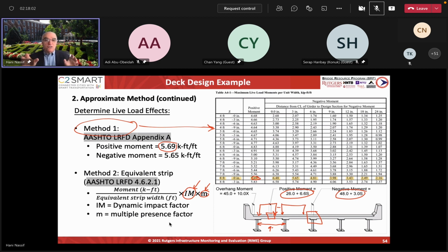In a girder, you can put one truck and then follow it by one truck. The whole girder will deflect under the effect of them. But here, it's the axles. And if you're taking the strip here, the HS20 truck is about 28 feet, so some of the loads will be distributed back to the strip because they have some effect on the strip. They are in the long direction, but you still have to take them into account. But the loads here are 16 kip each. So 16 kip, and then 16 kip, and then the 4 kip and 4 kip for the front axle, right?